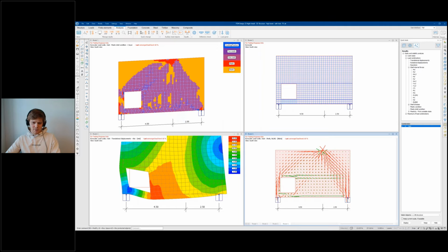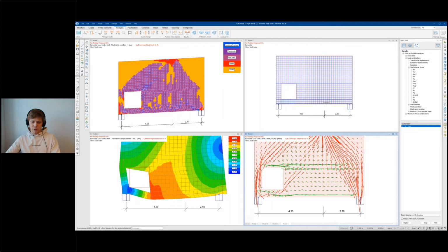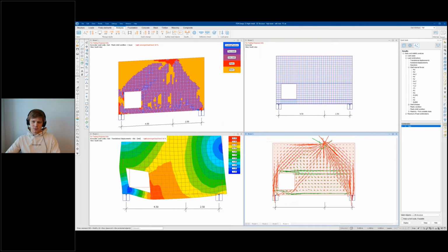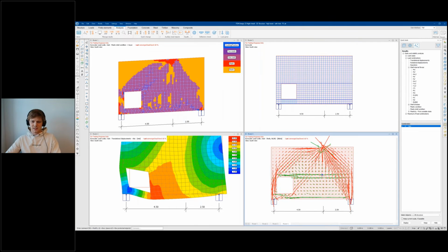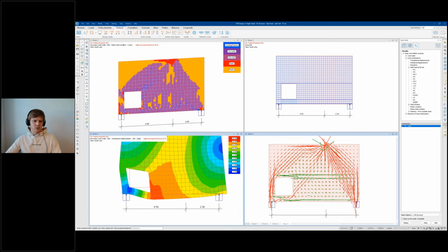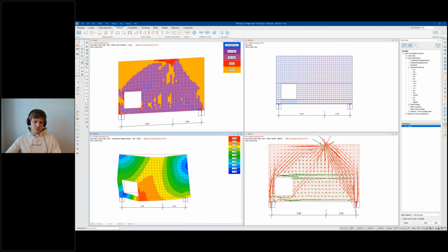With the tension parts, you can clearly see that there is a value that it reaches for all the standard rebar I put in, and then it can go quite a bit further for the concentrated and quite a bit larger reinforcement I put in as extra. So it will utilize what is available, and for me at least in this case, there is a huge difference between the elastic solution and the plastic one. So consider this a teaser, and a reason why you really should join in for Isaac and Johanna's webinar on this matter.